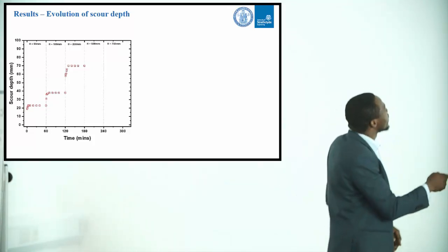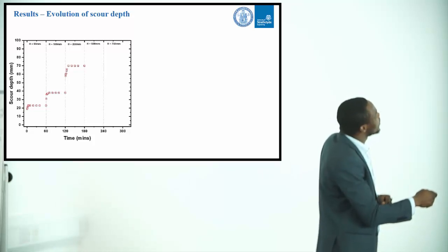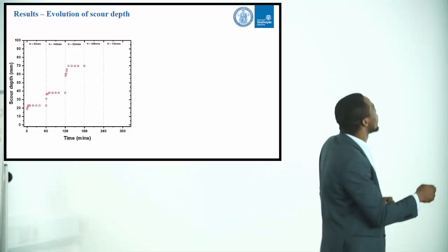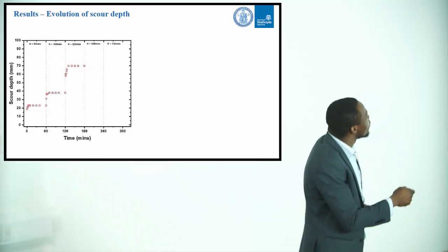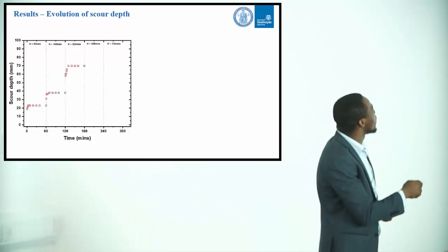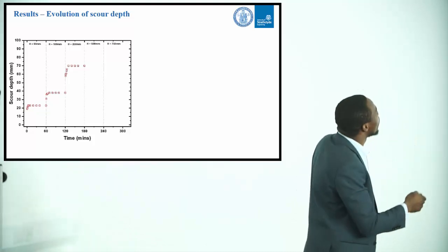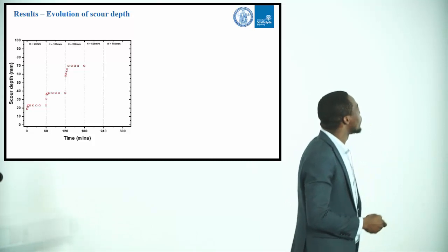And when the hydraulic head is increased in the jet tube, the scour depth again jumps and then quickly attains an equilibrium erosion scour depth, and then again up to 250 millimeters. I stopped at 250 millimeters because we already had almost 70 out of 100 millimeter depth in the soil. When we tried at 500 millimeters, just within 2 seconds, the entire soil had eroded.